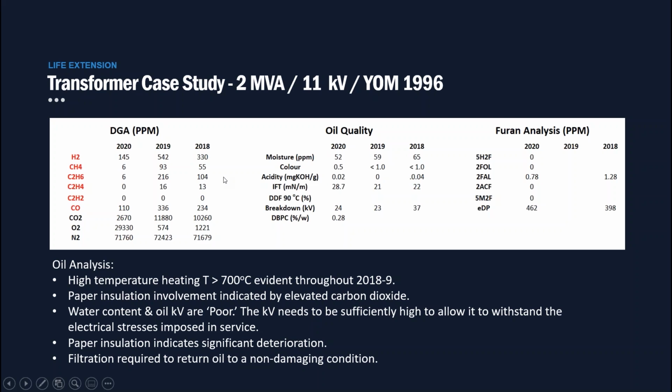It's a good result. The oil quality results are not good. The moisture levels are very high. The assessment is poor according to IEC 60422. Same with the dielectric breakdown voltage, very low. And a high breakdown voltage is needed for safe operation of a transformer.